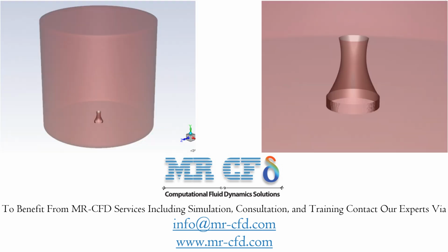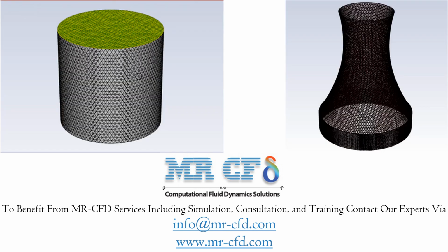The geometry of the present project includes a cooling tower, heat exchanger, flow domain, and an air inlet. The geometry is designed in Gambit software. The geometry is also meshed inside Gambit software. The mesh type used for this geometry is unstructured, and the total element number is equal to 1,343,988.